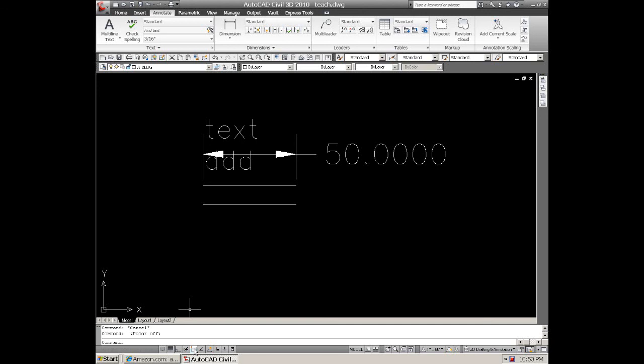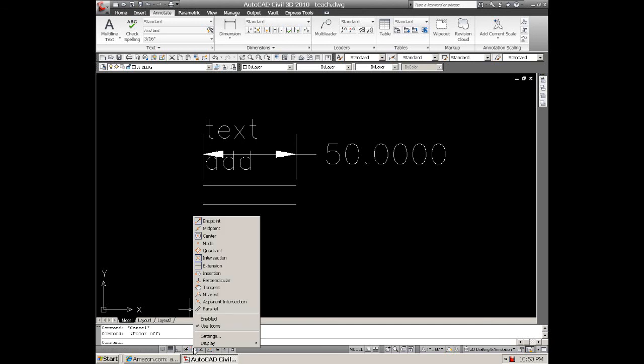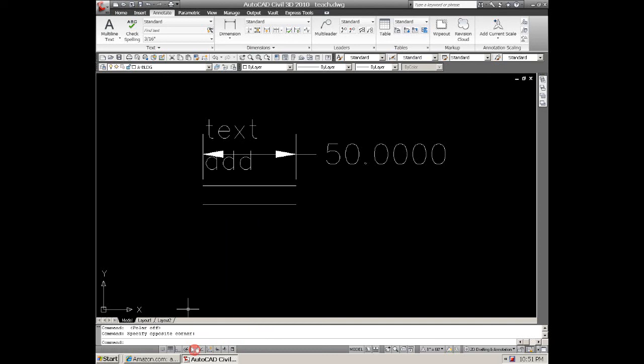Now if you want to change the features on any of these boxes, simply hit your right button, and you'll notice these squares around these is where your line's going to snap to if you use your line in drawing something. If you want it to go from one end of the line to the other, or center of an object, then that's where you click it to. Otherwise, if you don't want all those, you unclick them, or you can just unclick the box and make sure it's not highlighted, then use it again.